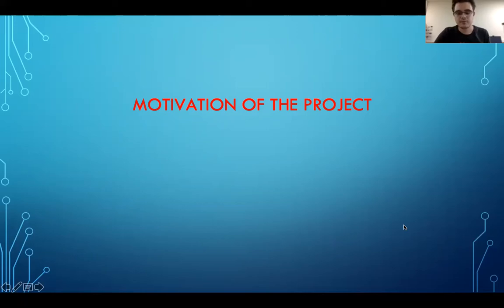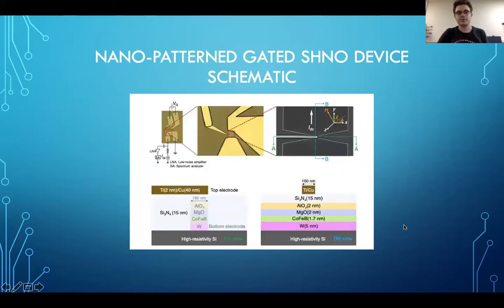We use voltage-controlled magnetic anisotropy to have this individual control over one spin Hall nano-oscillator. In this photograph, you see the device schematic from the microscope. These are the 4 contact pads. The top ones are used to apply the voltage difference. Voltage difference is applied from top to bottom in this photograph. And this is the more zoomed in version. And this is the extra zoomed in version.